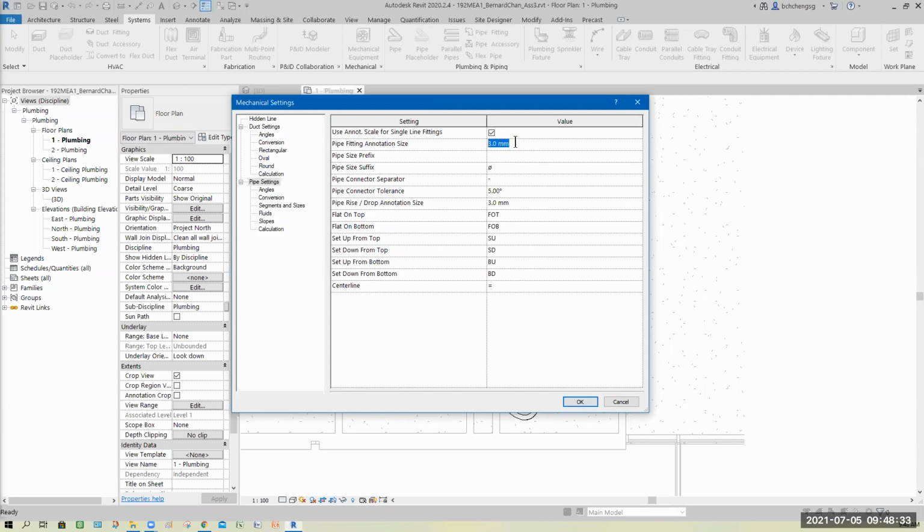So here I would like to adjust it. Let's say prefix, suffix, pipe size, diameters. This US version they put it behind. Here we want a diameter. How to place this diameter? See that? In Singapore, the diameter symbol we put in front, right? Correct. So how to put it here? Can I copy and paste?